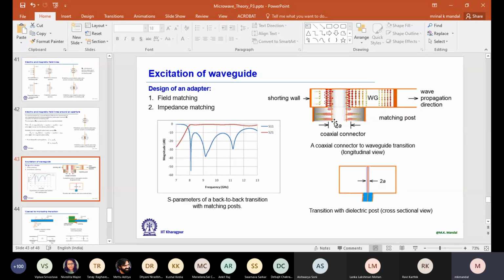Well, as I was discussing, you look here, this is actually optimized, designed by one of my students. Look at these parameters of this adapter, scattering parameters. It's not that great. In fact, for just a coaxial to rectangular waveguide without matching, it will be very narrow band.